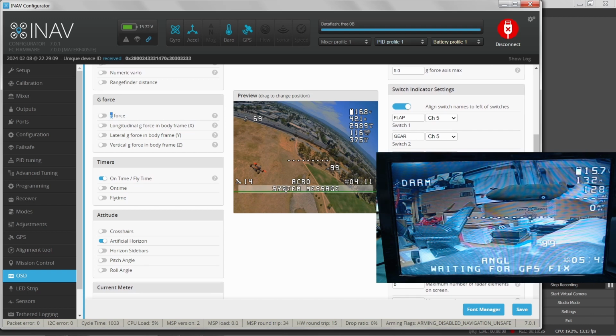the system message gives you information about the status of the flight controller. And right now it's telling me it's unable to arm. So if I were to try to arm the aircraft, it wouldn't let me. In fact, let me try it. Oh, I disabled my beeper. Let me re-enable that. That's telling me that I cannot arm. And this is telling me visually why it can't arm. It says it's waiting for a GPS fix. I've got 0 satellites right now. Earlier I was getting a satellite lock. Right now I'm not getting any satellites at all.